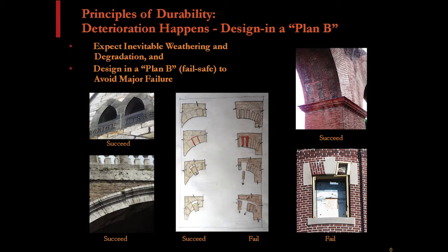And I think it shows the beauty of using a wedge-shaped brick, or in a lot of the Roman construction where they often used a wedge-shaped brick, and where they didn't, what they typically did was the mortar joint goes to basically zero at that inner edge. And I'm diagramming that here with the wedge shape, where you lose this mortar, the wedge shape drops, and it pinches in and locks into a new position of stability, and you don't have a collapse or a loss of stone, and you don't have a progressive collapse.